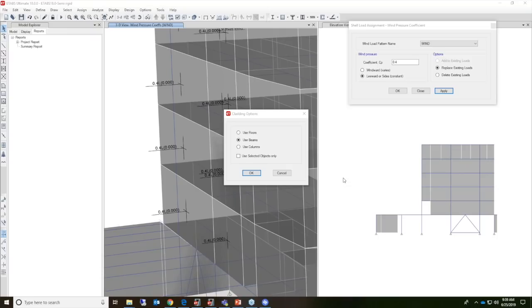Yeah, cladding is only for that. Is there any point to using the auto draw cladding function if you're applying user wind loads? Auto cladding is only to apply wind loading via the cladding elements, correct? Yeah, you're fine. Yes. That is correct.